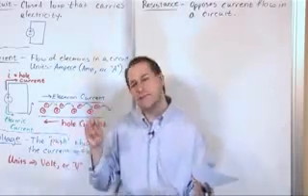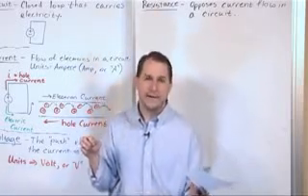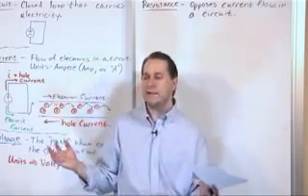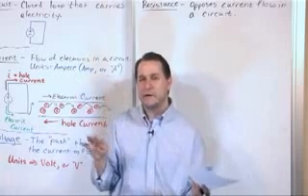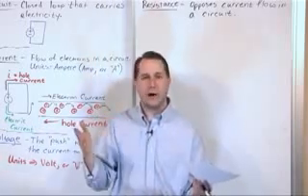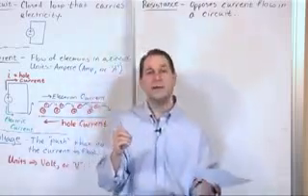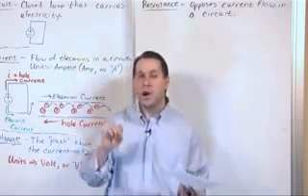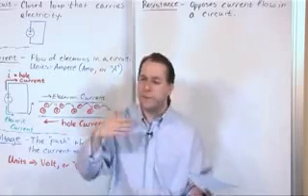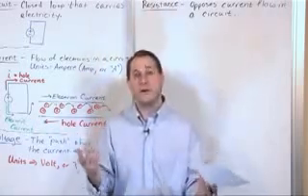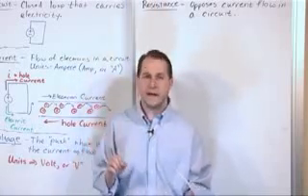So we say that the resistance, for lack of a better word, of this guy to airflow is not very big. It's got a low resistance, right? Now let's compare and contrast that. Let's go back to our coffee stirring straw. Very, very tiny diameter. So for that one, to get any kind of air movement through it, I've got to blow pretty hard. And I can feel it in my lips. I'm really blowing because the resistance of that smaller straw is much higher. The resistance to airflow is higher because it's physically constrained. You cannot force that much air through that straw very easily. I mean, you can do it, but you have to blow really hard. So we say the resistance is much higher for that guy.